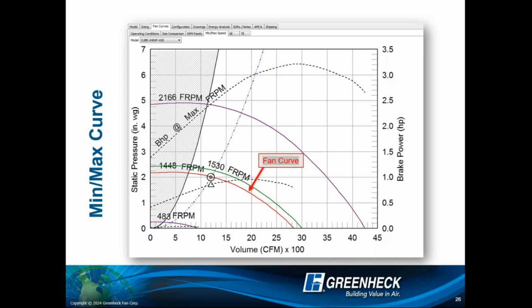And I have had a few questions, by the way, about how the system curve is defined. That system curve right there, the dotted line going up, the blue one, that's always defined by your static pressure calculation of the ductwork. And when you're applying the fan laws, the only way to apply the fan laws properly is on that dotted line. Okay, so the fan laws wouldn't necessarily work if you don't have that ductwork calculated correctly, right? So we're dealing with ideal conditions here.